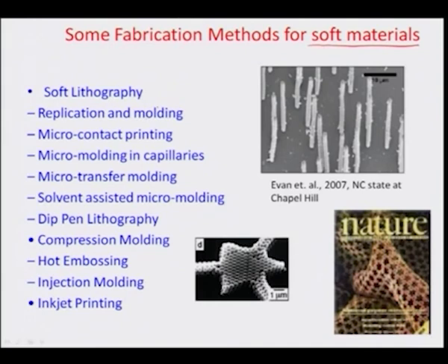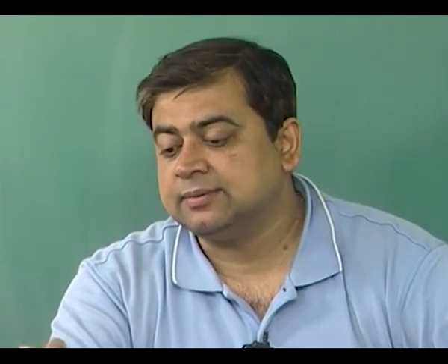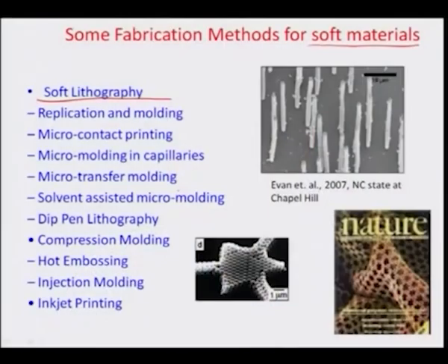And the domain of process which is used mostly for the fabrication of these soft materials is also known as soft lithography, just because you are using soft polymers, and you have to use one step of lithography, and the mold that you eventually create can be used many times to have the soft material molded again and again across that mold. So, you have one step lithography followed by soft material driven micro molding, which would result in features and structures at the micro scale, and you can prototype it very, very rapidly as well.